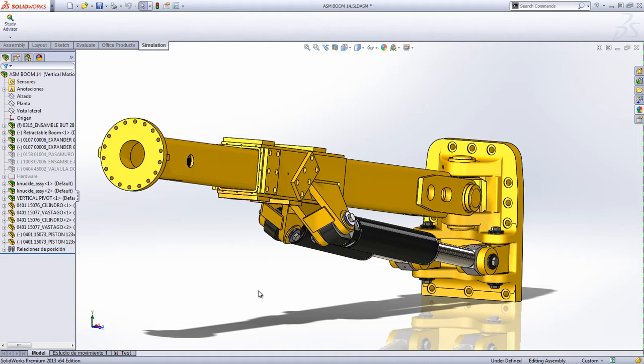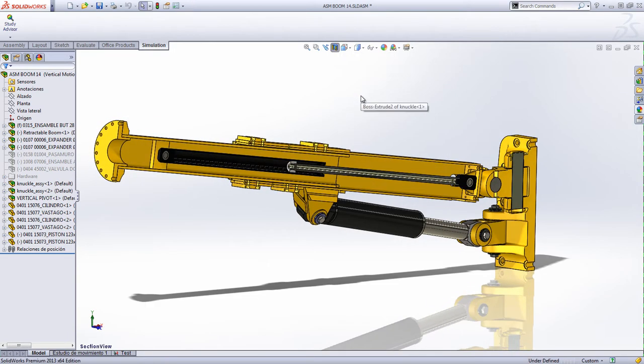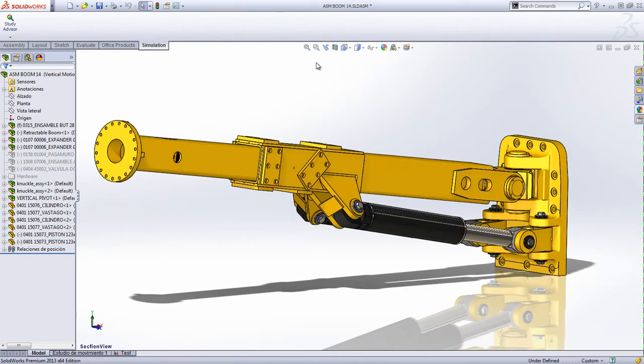In the main demonstration, we've seen how SolidWorks simulation helps in quickly sizing parts, but it has far more capabilities to help in meeting many design challenges. In determining performance of the overall boom design, we can use SolidWorks simulation to quickly locate high stress areas in need of more detailed analysis. The boom contains two main actuators that combine to raise or swivel the arm, and an internal actuator for extending the boom out.